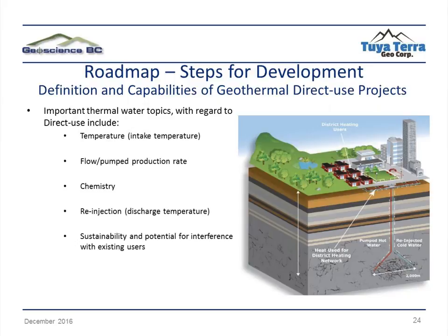But another very important thing is reinjection. Reinjection will keep our system going. It is one of the most technically challenging parts of geothermal development to get reinjection correct. What I mean by that is we don't want to cool our upgoing fluid, and we don't want to have a drop in pressure. So reinjection is a very important part of what we're going to be doing.